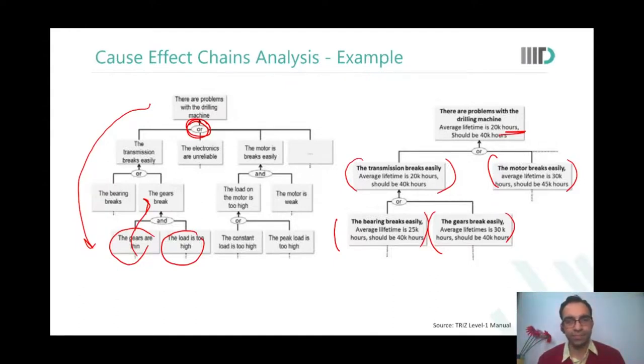Hello, sir. I was thinking that making this graph would also be a challenge, because I was thinking of one of the problems you gave in our first class of creativity, related to the writability and write speed of a SRAM cell. The existing problem was putting body bias on those pull-ups and accordingly improving the write speed. The solution was already existing, but no one found it out. But when we represent this whole thing in the form of a graph, how do we represent those kinds of conflicting things? I was not able to figure that out.